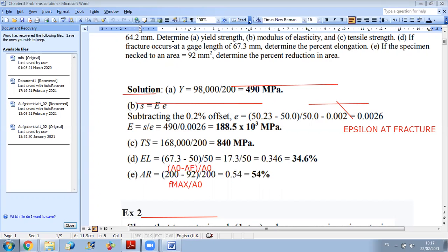And these two indices can be a characteristic of ductility. Okay, so ductility can be measured through percent elongation and through area reduction. And the higher the percent elongation and area reduction, the higher the ductility of the material. Okay.